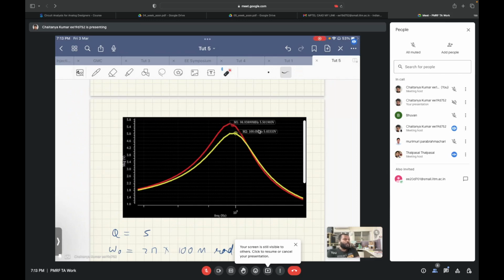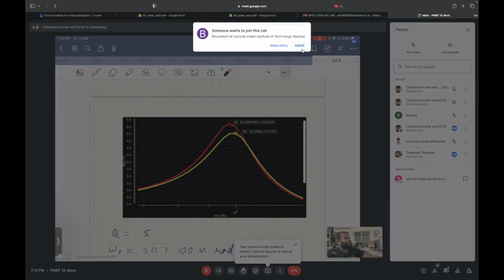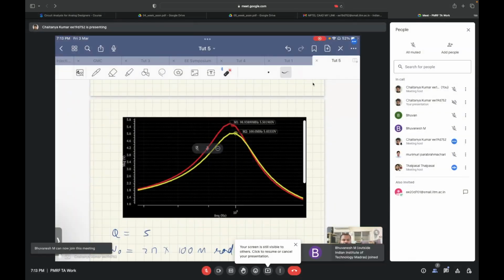And with that, what you will learn is, one thing, definitely your accuracy will improve. Other thing is, you will learn the technique of debugging. For example, one of the nodes, you wanted something but you are getting some other value on that node. In that case, you will start looking from the first node itself. At the first node, this transfer function should be there. Are you able to get it or not? If you are able to get it, then you will understand how to debug your mistakes. So all these things you will be able to do.